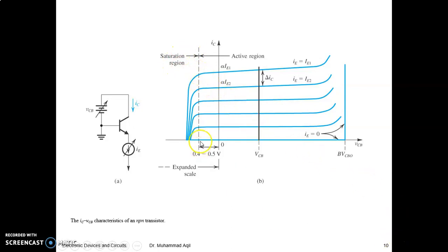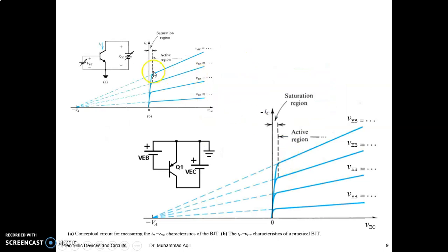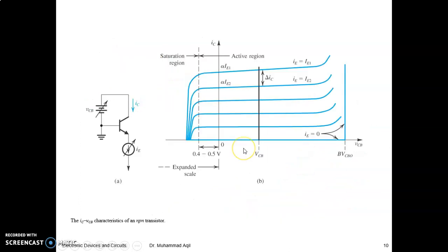And from 0.4, minus 0.4, over to VCC, it remains in the active region, right? Whereas here from 0 to 0.3, because VCE is 0.3, at VC 0.3 your collector base junction becomes reverse bias. So you have actually visualized the active region here.